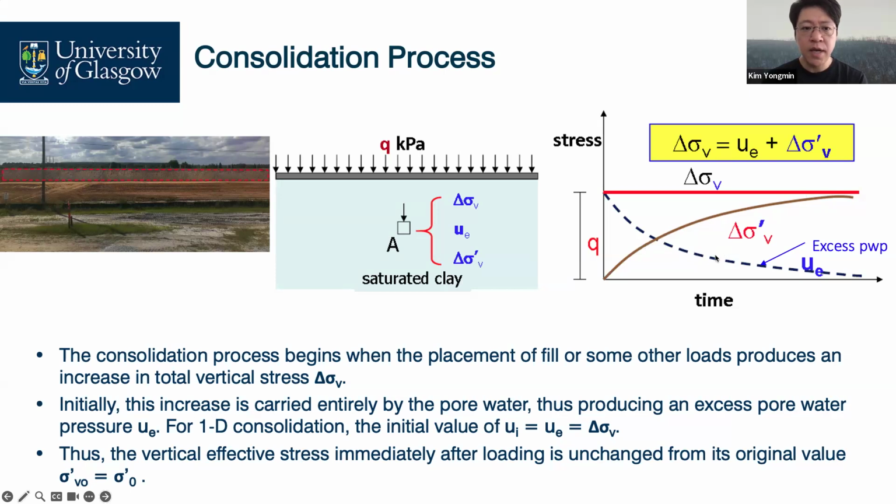At the end, excess water pressure becomes zero. Then your Q, the additional surcharge, which I initially mentioned as total stress, at the end becomes effective stress.